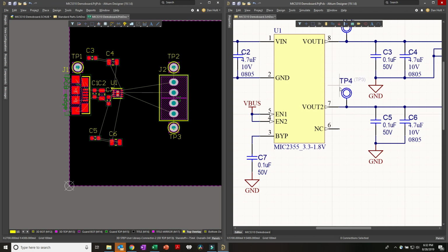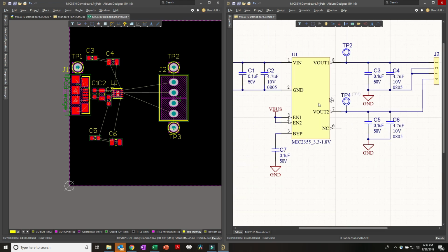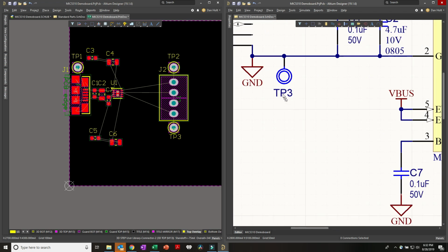These jumps are too big, so while I'm still holding my mouse button and dragging, I'm going to press the G key, and down here, see this grid 100? If you look at that for a second, while I move this, if I press G, it's going to adjust to a new grid. So that let me put that designator a little more appropriately.